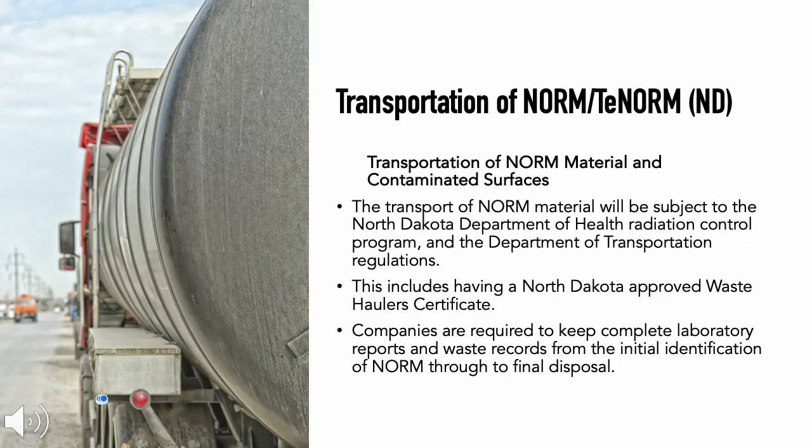With that being said, we'll talk about the transportation of NORM. Transportation of NORM materials and contaminated surfaces: the transportation of NORM materials will be subject to the North Dakota Department of Health and Radiation Control Program and the Department of Transportation regulations, or DOT. This includes having a North Dakota approved waste hauler certification. Companies are required to keep complete laboratory reports and waste records from the initial identification of NORM through to final disposal of the NORM material.